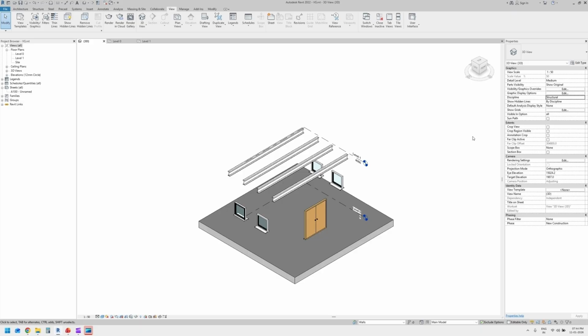In this instance, your walls are turned off. They don't have any issues with categories, filters, workset, etc. But because your view is set to structural, you won't be able to see any architecture walls. Sometimes the issue is not with the elements, families, or links, but the issue with the discipline.